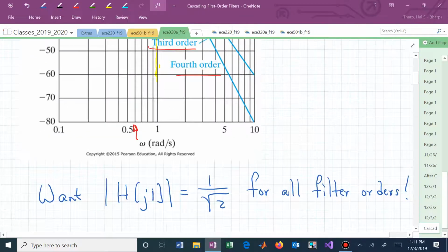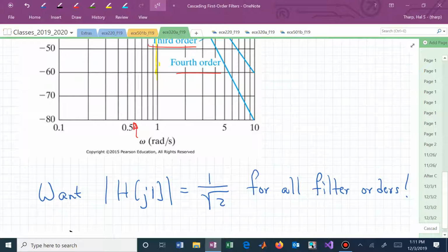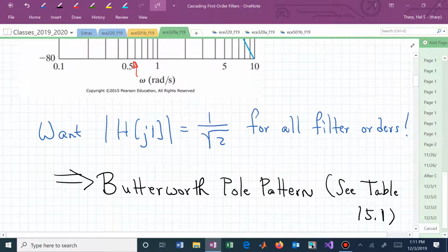So what we want is H at j1. 1 is our normalized cutoff frequency. We want to maintain that at 0.707, or 1 over the square root of 2, for all filter orders, for n equal 1, for n equal 2. We don't want this behavior that we're seeing in 15-16. And that now says, oh, we need to have a different pole pattern. Now we need a Butterworth pole pattern to maintain that flatness in our...